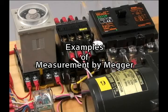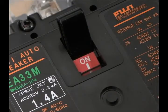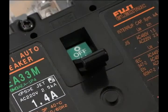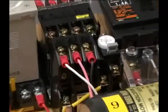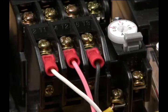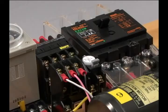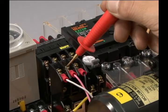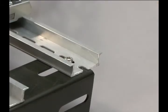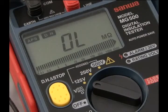Here, let's see how to measure a motor's insulation resistance using a megger. Before measuring the insulation resistance, turn the MCCB off. Unless the motor is dismantled, the coil will not be visible. However, insulation resistance can be measured at the MC output terminal because the motor coil is electrically connected to the MC. So, use the megger's plus side test lead, red, to touch the MC output terminal. Use the other lead, black, to touch the ship's hull or the terminal to which the motor's ground wire is connected.